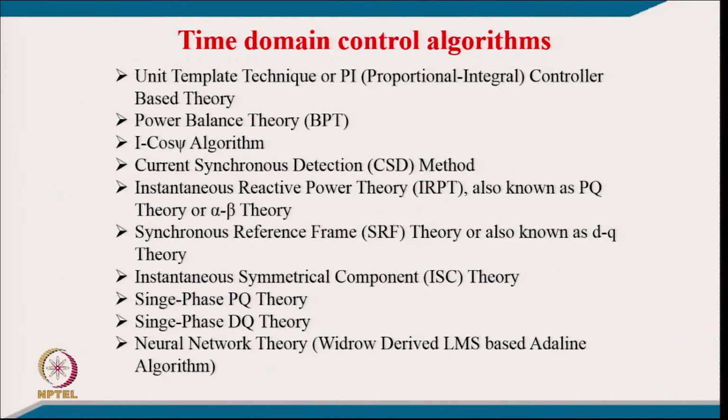Then we go to synchronous reference frame theory, which is also known as DQ theory and based on Park transformation. Another control algorithm is instantaneous symmetrical component theory, based on the symmetrical component concept. Then we go for single phase PQ theory. These are based on the single phase concept, but applied for 3 phase as well as single phase, and single phase DQ theory can also be applied for single phase as well as for 3 phase.